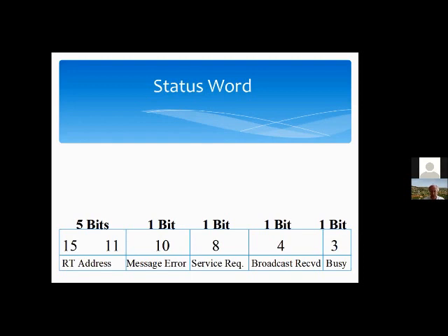But the handbook says you might use 16 words of data for some things, 32 words for other things. All that kind of stuff is not part of the spec. And in any event, when you actually have a project, whatever RT you're involved with is going to have to publish a book of exactly what data it expects to get in and what data it expects to send out, what the formats are.